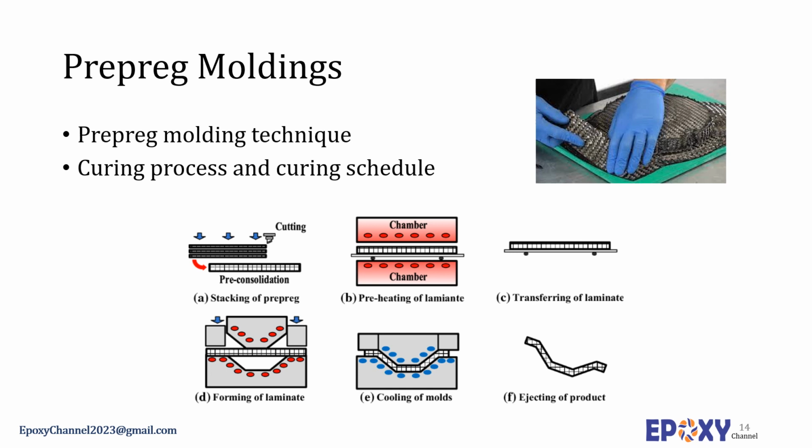The bleeding of excess resin facilitates the removal of entrapped air and residual volatile impurities during the consolidation of the prepreg into a void-free laminate. Due to the exothermic nature of the chemical reactions and the risk of temperature buildup in thick sections, the curing schedule should be carefully controlled. Prepreg molding techniques have a complicated technology, but offer the mechanical engineer the opportunity to orient fibers in the direction of the principal stresses within complex structures.